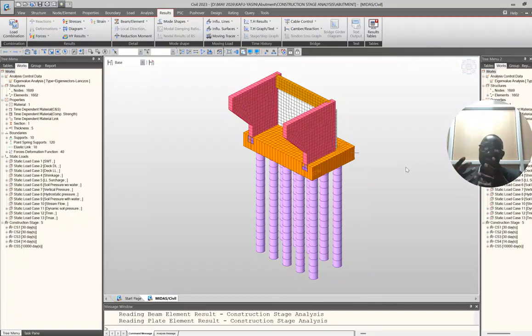Do your piling, then later on do the pile cap, after which you get into the abutment and you complete with the ballast wall. Then you apply the loadings, and you see how the loads get built up in terms of deformation and loading. So you do your normal modeling, which we have done. And this bridge I did, this abutment has a scour depth of up to 17 meters.